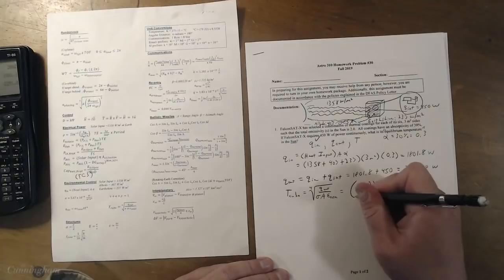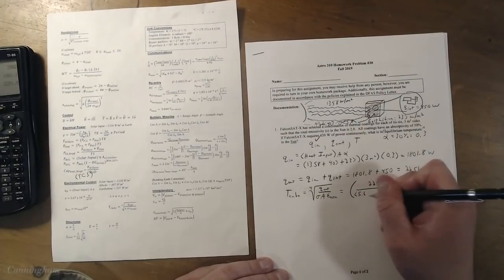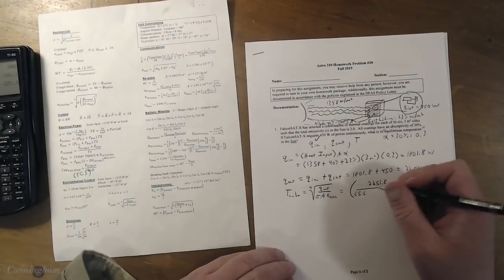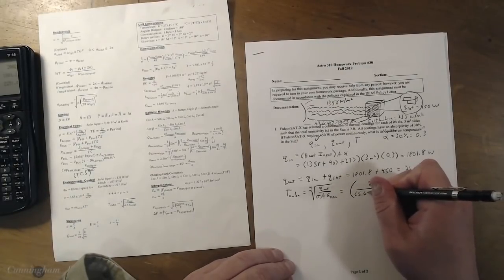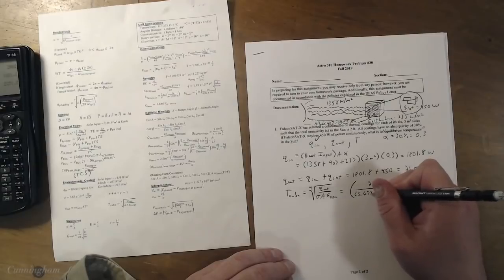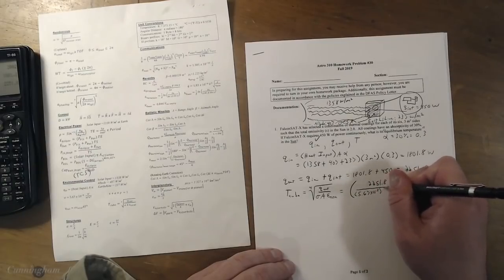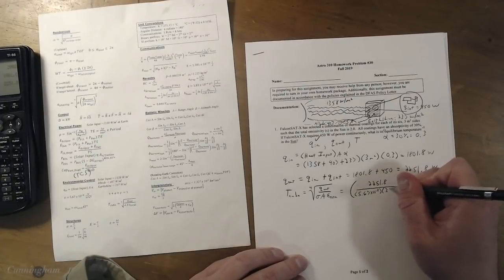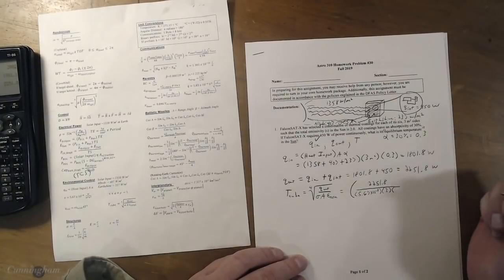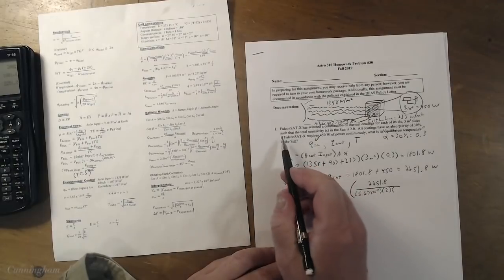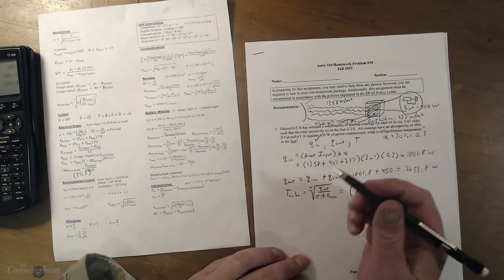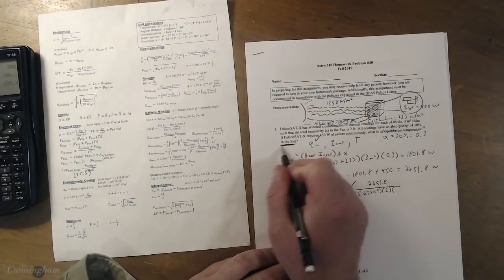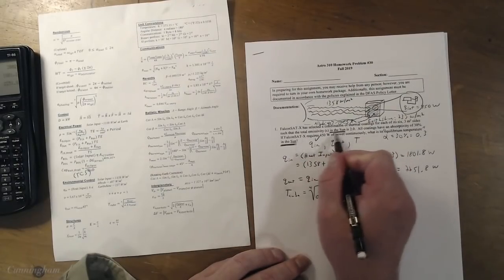Good. Stefan Boltzmann is on your equation sheet where? Let's see. It is right in the environmental control area, because that's pretty much the only place we use it. Again, I want to call it thermal control, but it's the same thing. 5.67 times 10 to the negative 8. And then, of course, 3 meters squared on one side. And the total emissivity, they tell us, total emissivity in the sun, which we're assuming it's in the sun right now. What is the equilibrium temperature in the sun?